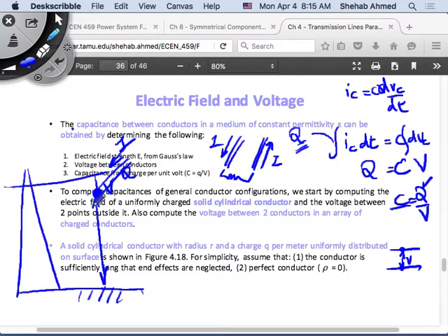Because I will show you later that if you have 3-phase conductors put in this arrangement, this point here will be a ground potential as well, because the electric fields from these conductors are going to add up vectorially, and they will sum up to 0 at this location. So it's like calculating the potential difference between this conductor and ground, between the conductor and some neutral point with a potential of 0, basically.